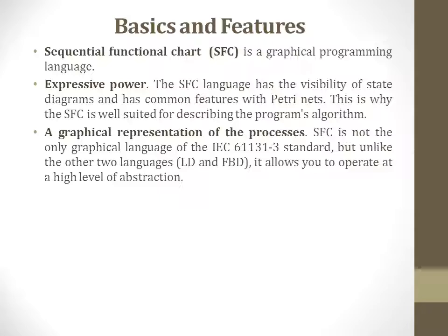SFC is not the only graphical language of this standard, but unlike the other two languages, LD and FBD, it allows you to operate at a high level of abstraction.